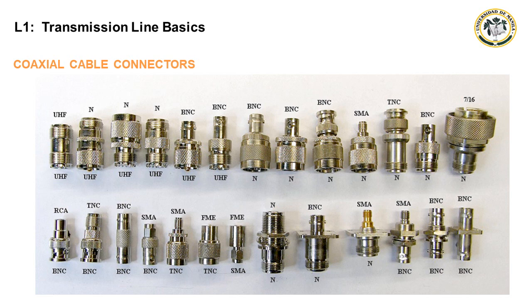Coaxial cable requires special connectors that will maintain the characteristics of the cable. Although the inner conductor and shield braid could theoretically be secured with screws as parallel lines, the result would be a drastic change in electrical attributes resulting in signal attenuation, distortion, and other problems. Thus, coaxial connectors are designed not only to provide a convenient way to attach and disconnect equipment and cables, but also to maintain the physical integrity and electrical properties of the cable.